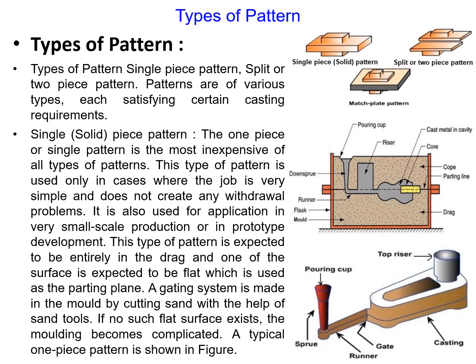Pattern types. There are three major types of patterns available. First one is solid or single piece pattern. Second one is split or two piece pattern. And third one is match plate patterns. You can see all three types of patterns in this first figure, and the two remaining figures belong to